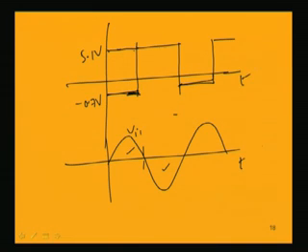Here we are showing an example where we can limit the output voltage, which in the ordinary zero crossing detector was around the V saturation voltage of 14 volt or minus 14 volt. That is too high a voltage.